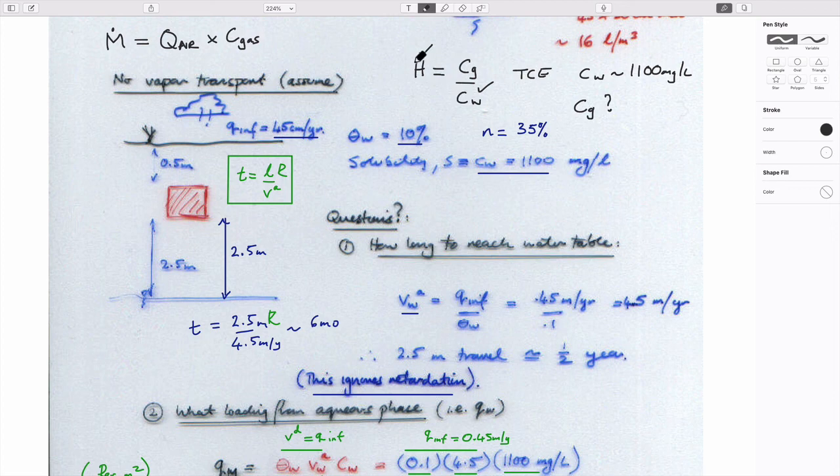If we know the Henry's Law coefficient, and we know for any particular component the aqueous solubility, the maximum concentration, we can then get this value. Once you know this, and if you prescribe a volumetric flow rate, you could just look at pumping that volumetric flow rate across here and get a rough idea of how quickly you could remove the mass.